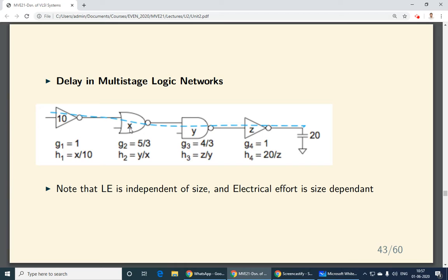And that is one of the advantages of the way we have defined it also. If I have to know X to calculate the logical effort, then it's impossible to use this method at all. Okay. So for that reason, here also two input NAND gate, I don't care about this Y. The logical effort is 4 by 3. Similarly, inverter, I don't care about the Z. Logical effort is 1. So if I have these things, what is the logical effort of the path?